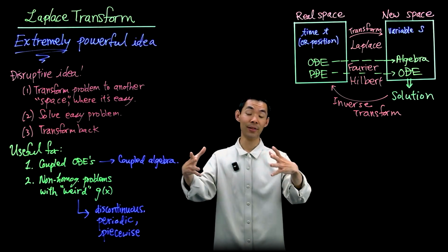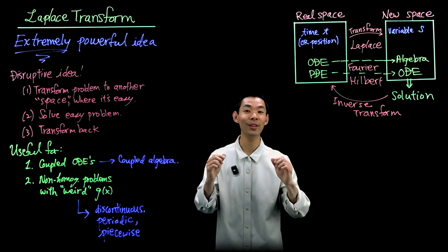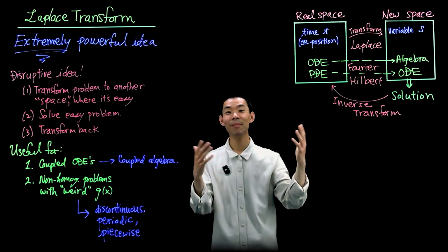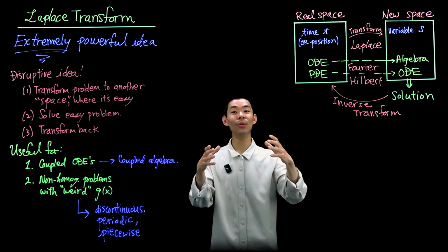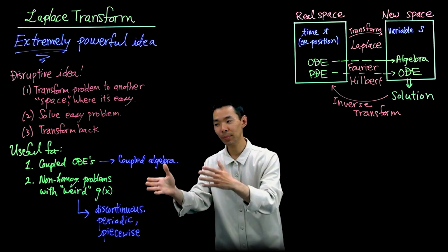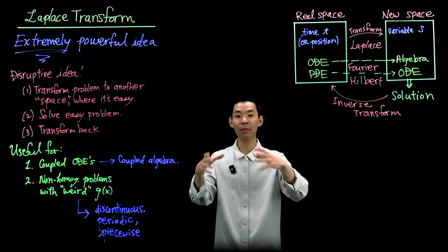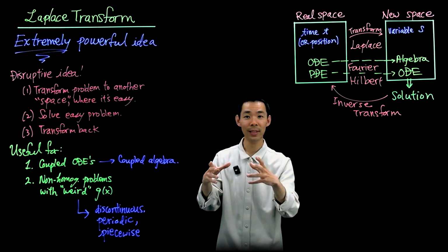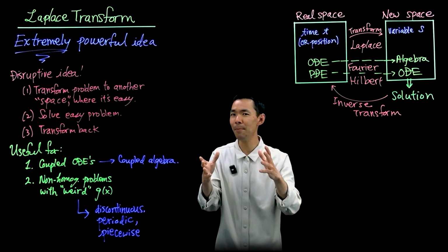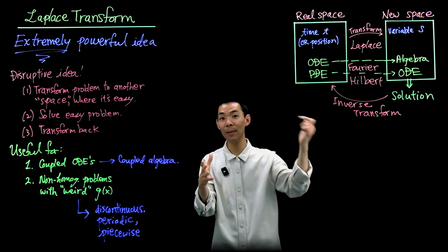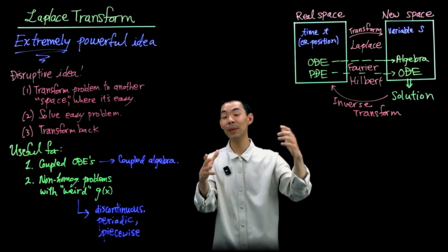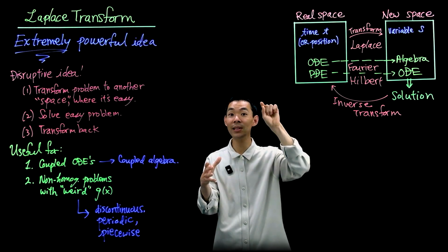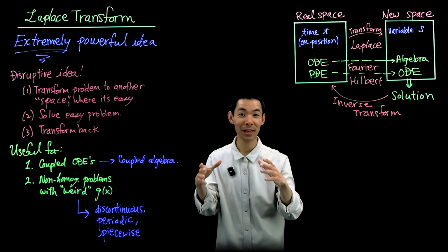Suppose you're building a reactor. You have some kind of reactants turning to products. And you're dumping in some kind of new reactant C into the reactor. And how you would explain that mathematically is, say, I have a reactor going. It's got equations of motion that describe how the reaction is proceeding. And at some time t, maybe 10 minutes later, I want to start dumping in a third component, concentration C, or species C, into the reactor. That would be kind of like a pulse or a step function happening at time t equal to 10 minutes.